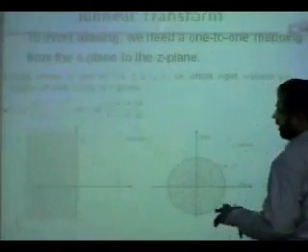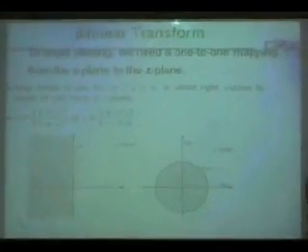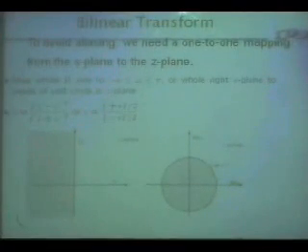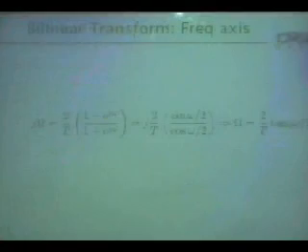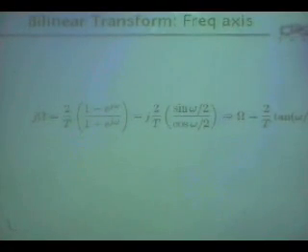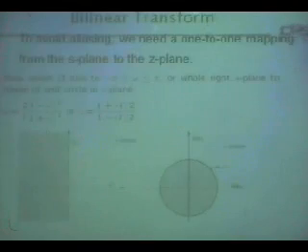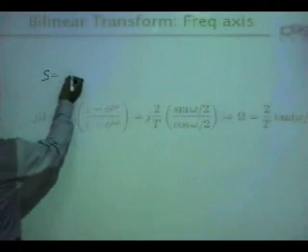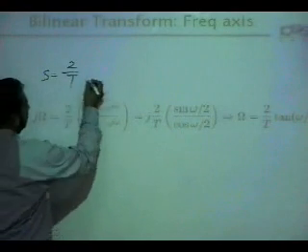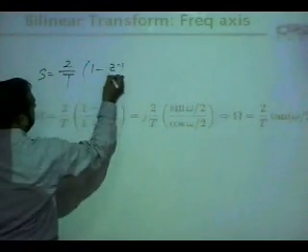And we'll generalize this. This is just for this example, and we know that a pole in S will map to only one pole in Z. So 1 degree will result in 1 degree in the Z domain. So if you go back, you see that we started with S equal to 2 over capital T, 1 minus Z inverse over